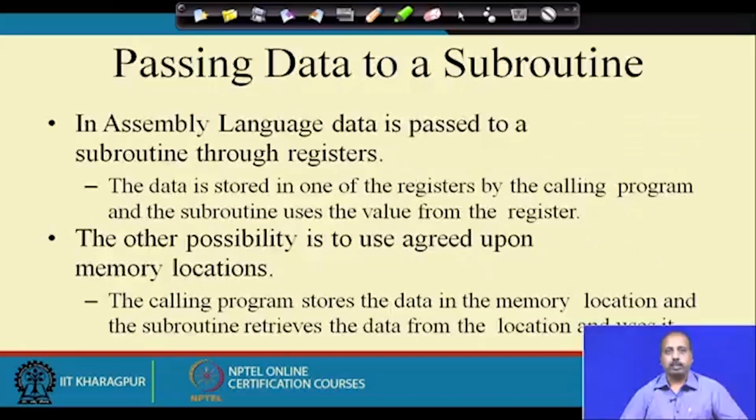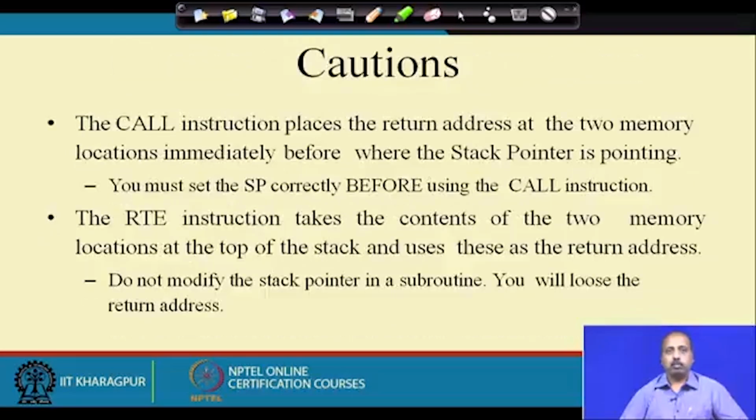Now, there are some cautions. The call instruction places the return address at the 2 memory locations immediately before where the stack pointer is pointing. Some time back I was saying that before starting the actual code of the program, we should set the stack pointer to some proper value.